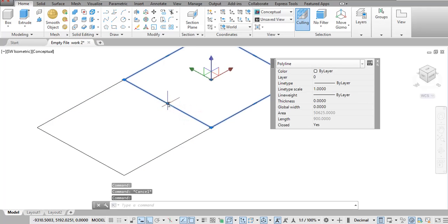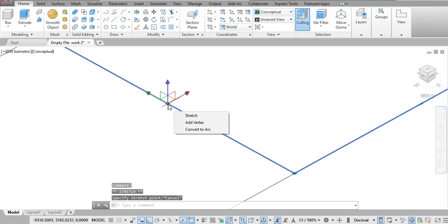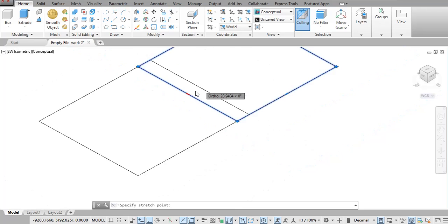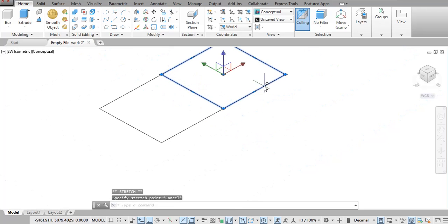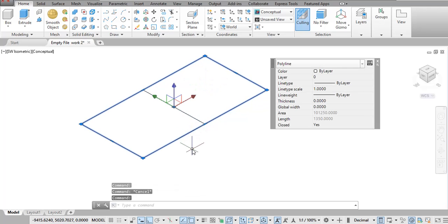So we click one of the half, then pick the center point, drag off, because we say we're going to make the thickness of the block wallings to be 25. So what we do is to offset this very outer layer of it.